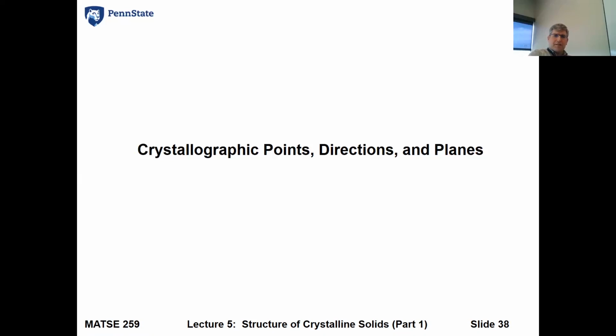Now, in the electronics industry, these are important mostly because materials like silicon and germanium and other things that are widely used in that industry really rely on very specific planes of atoms, or what we consider to be orientations within each of the crystal structures, in order to provide the properties that they're looking for. Structurally, these points, directions, and planes are also important, but on a much larger scale, because they determine where crystalline defects flow, and that allows us to look at plastic deformation, yielding, yield strength and tensile strength, all those mechanical properties that we talked about in the first lesson.